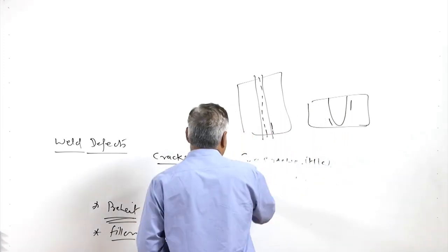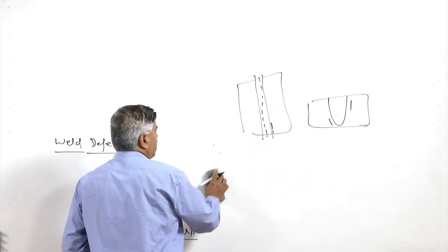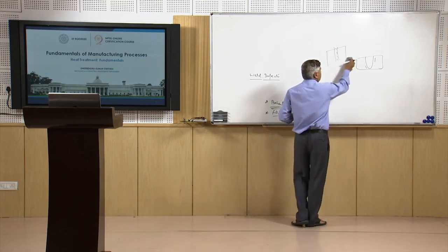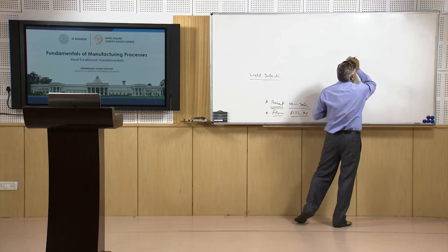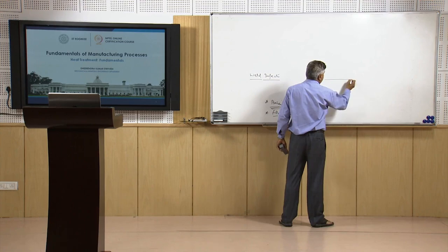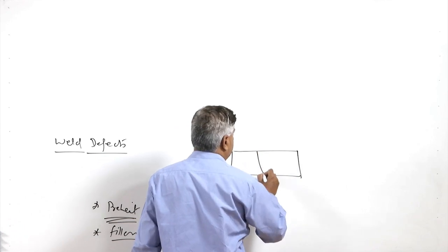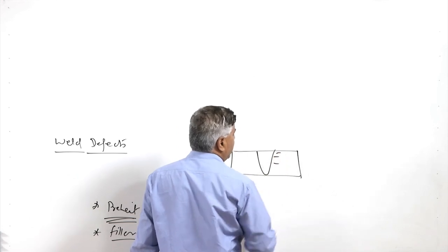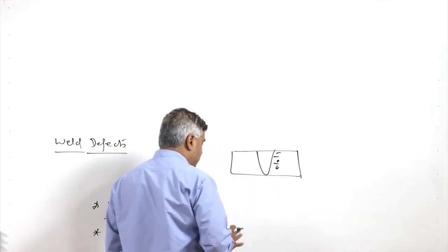Since this kind of crack is formed below the weld bead, that is why it is called underbead. And mostly the main cause of the underbead cracking is the limited through-thickness ductility, which occurs due to the presence of silicate inclusions in the steel. So, under the tensile residual stresses, these tend to delaminate, or separate, from the metallic matrix. Say for example, this is the weld joint, and if the tensile residual stresses are being developed and inclusions are running in this way, then the separation of the inclusions from the metal matrix can lead to the development of the underbead cracks.